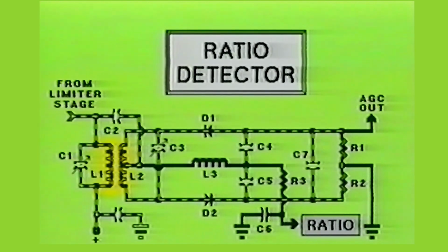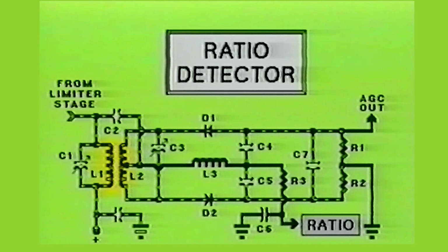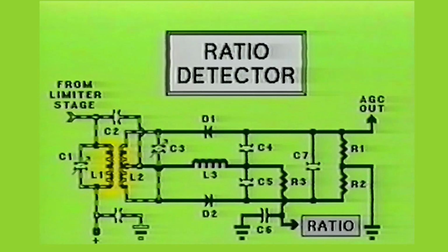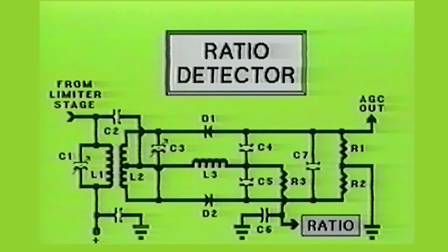With the circuit balanced, the equal charges in capacitors C4 and C5, the ratio of voltage will be 0 at the output. Capacitor C7 maintains a steady voltage potential across the top of capacitor C4 to the bottom of capacitor C5, so amplitude variations in signal strength won't affect the overall operating range of the ratioed output.